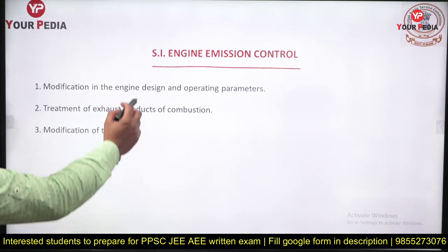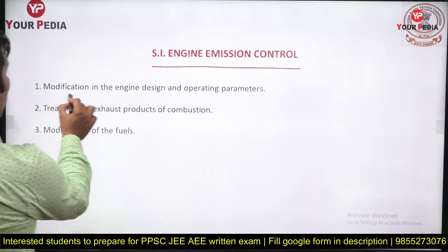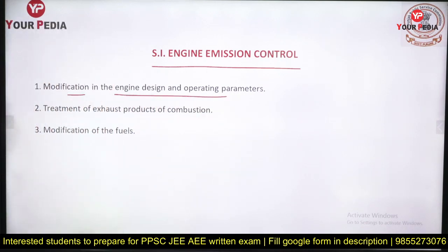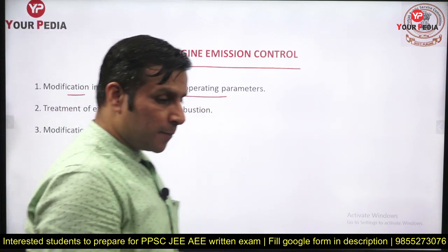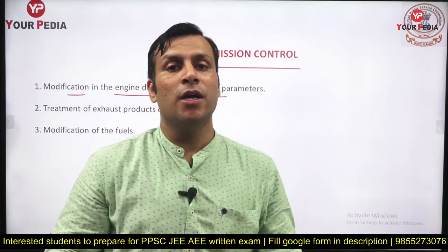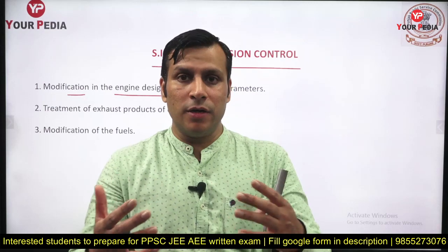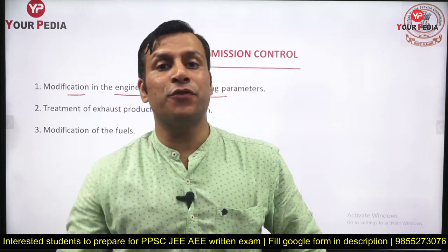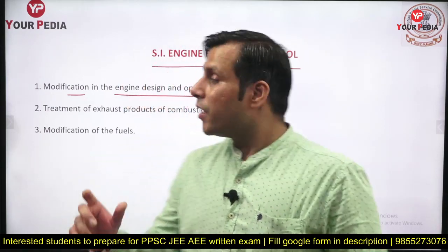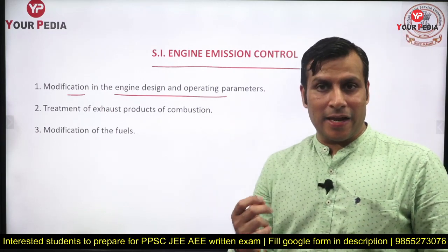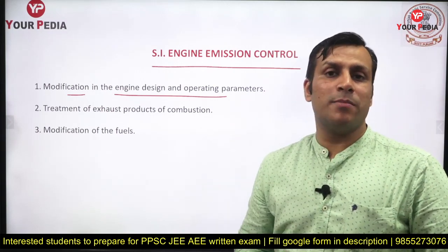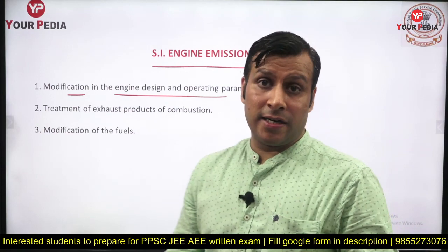So guys, in the SI engine, if you want to carry out the emission control, you can carry out some kind of modification in the SI engine. Modification in terms of what? You can design the engine so that there will be very good turbulence, so that the air fuel mixture will be good. Each and every fuel particle will get sufficient air. So first, there is a requirement of designing the engine in a very accurate manner. Okay, the combustion chamber design, the overall engine cylinder design.